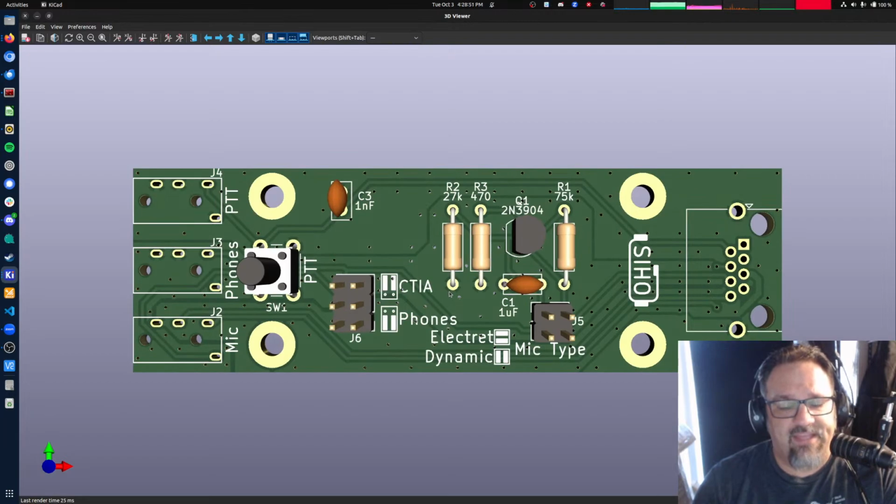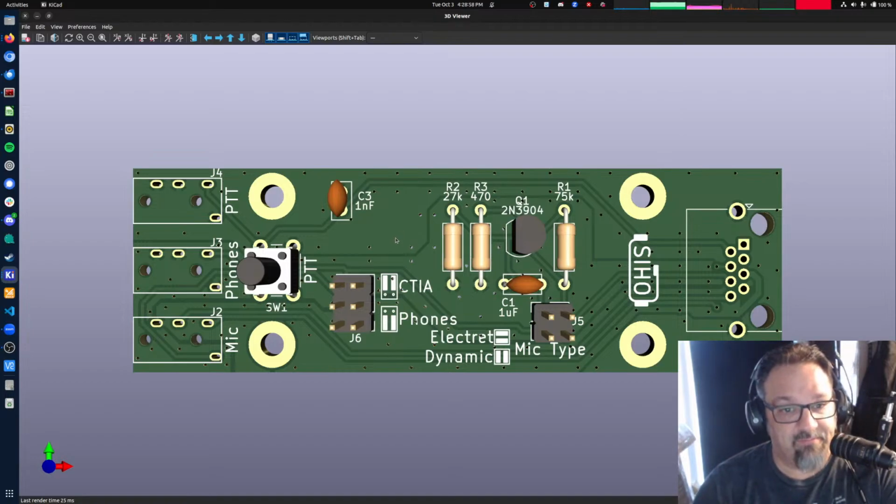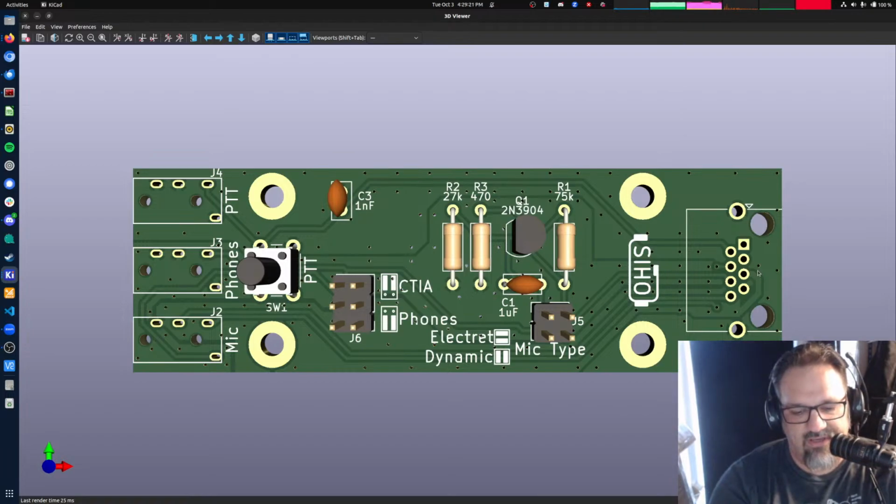And so if I do the surface mount one, I will probably make it with 1206, which are large surface mount components, to make it easy for new people to solder themselves, and just minimize the number of wires poking through the bottom, hopefully down to 0. And although doing surface mount RJ45s is non-trivial,